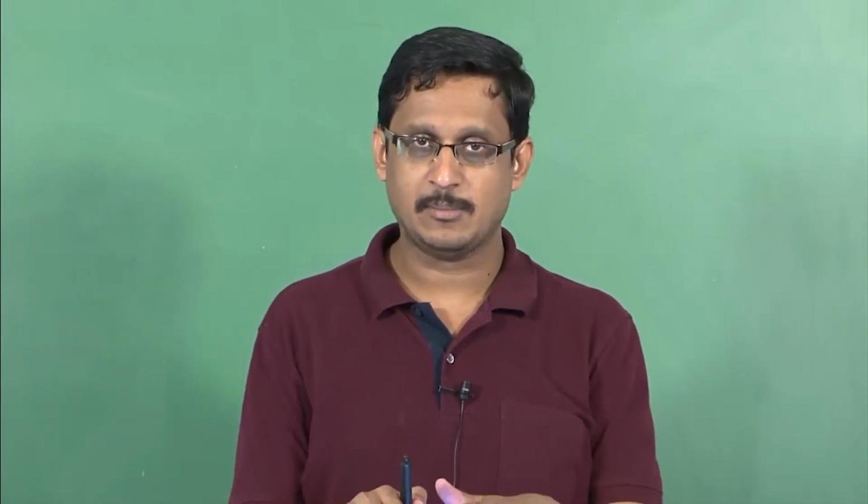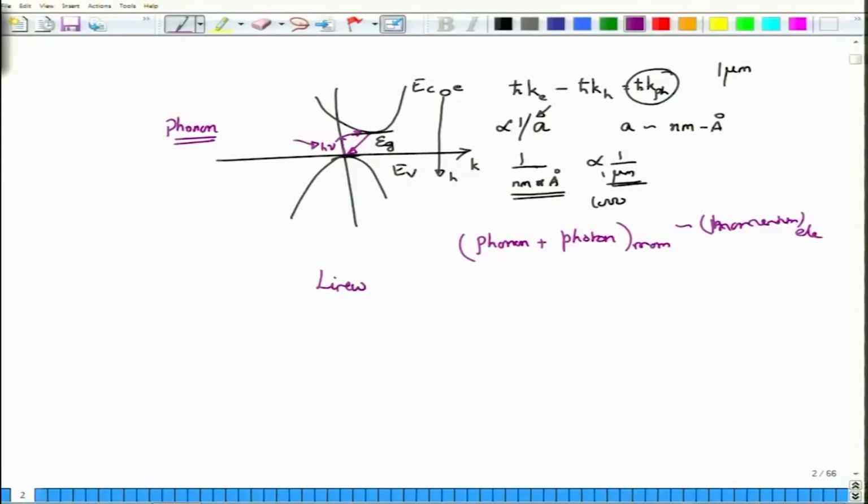So, this is some absorption characteristic, and what is important about this one is that the line width is essentially proportional to the temperature, because increasing temperature increases the spread delta EC and delta EV, which increases the range over which emission can happen.